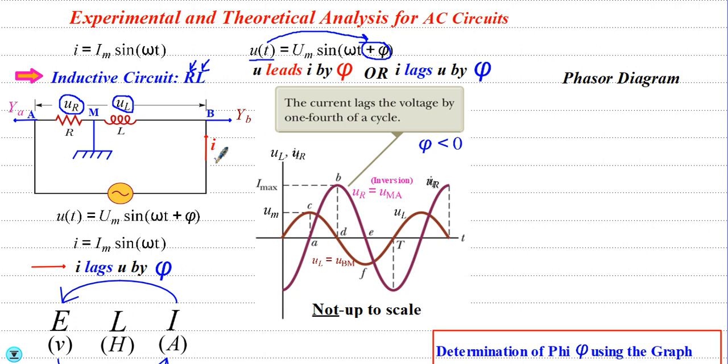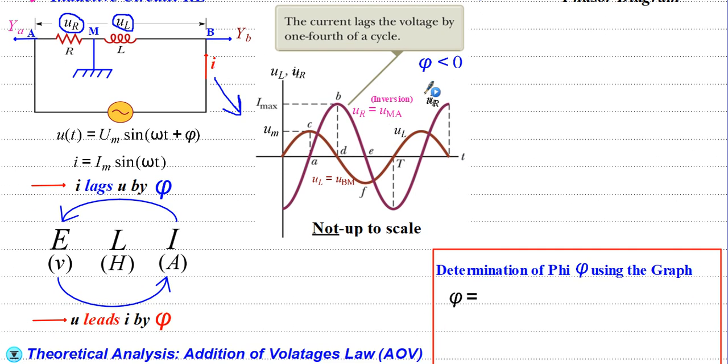So when we connect the oscilloscope to this circuit, the oscilloscope will give us these oscillograms. The brown oscillogram is U of L. The current goes from B to M, so it is UBM, so it is U of L. However, the violet curve or oscillogram is U of R, it's actually UMA. So UMA is positive, but actually the oscilloscope reads phase first, then the component, then ground. That's why we make the inversion so that we get these graphs.